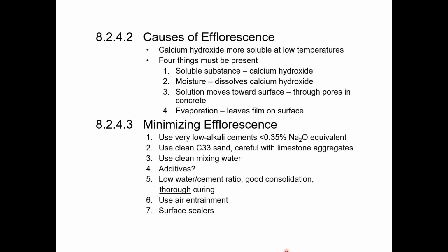So if those differential cambers represent the need to add all of a sudden another inch of topping slab, you've now taken out an inch of that residual capacity that those double T's had, because you put it back as a cast in place dead load. So those things have to be considered. To your point, small variations can be masked with secondary pours, but I wouldn't depend on that, because you could end up creating other issues.